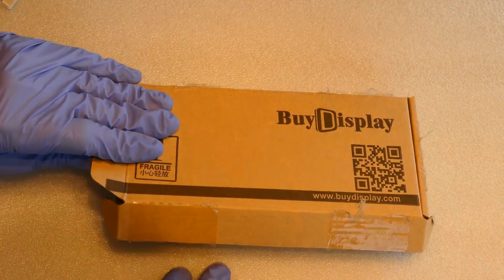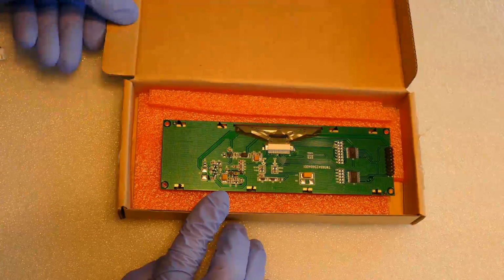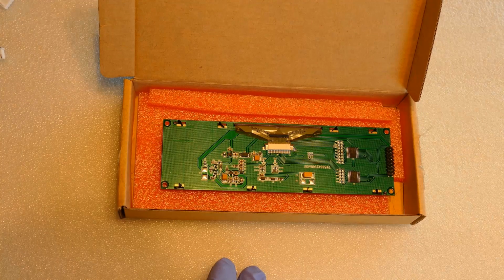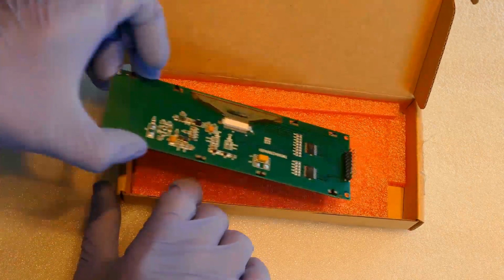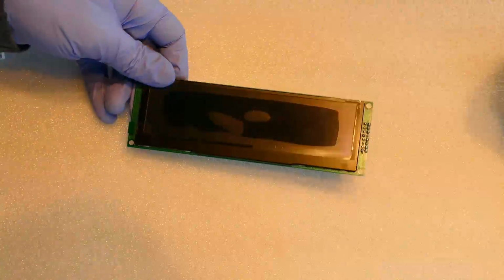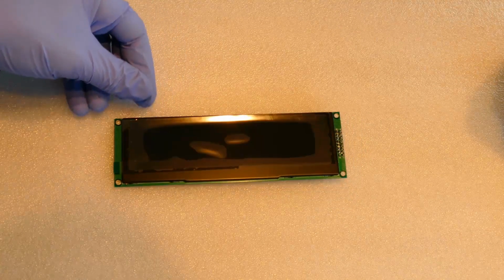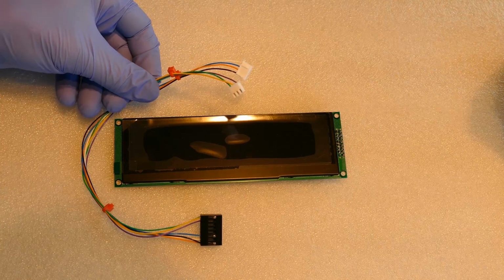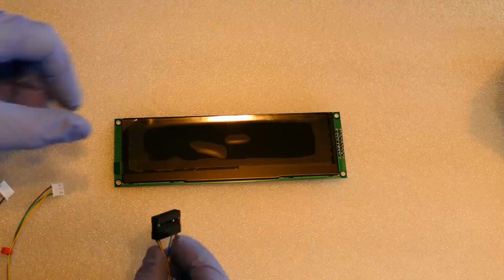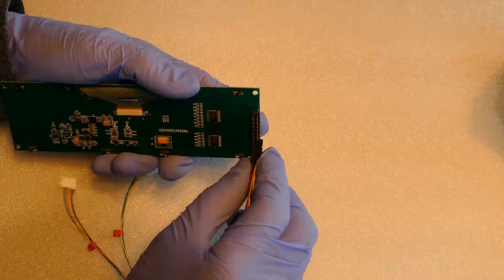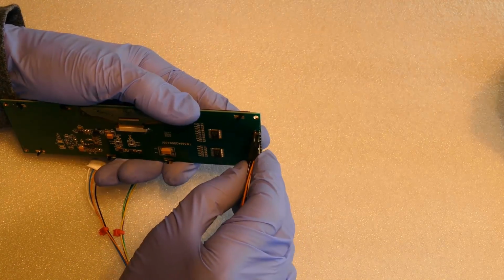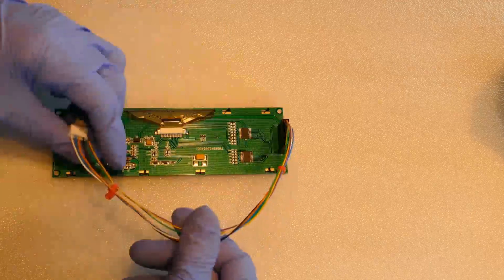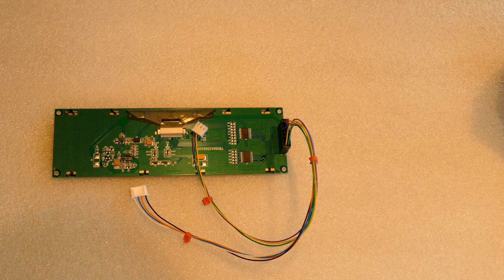Here's the green OLED display. I ordered the module as opposed to just getting the display with a ribbon cable. The module handles the communication and provides a 2.54mm header for easy connection. I crimped together a wiring harness using 3 and 4-pin male JST-XH connectors from my custom PCB and a 14-pin female pin header that plugs into the back of the OLED display.